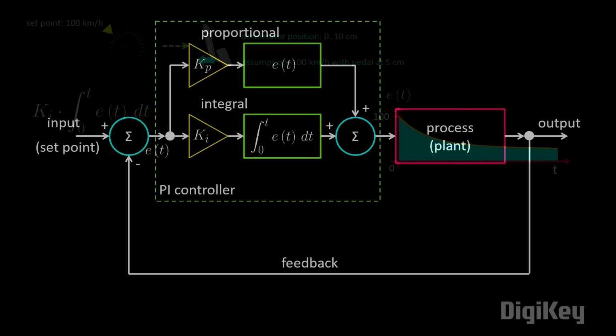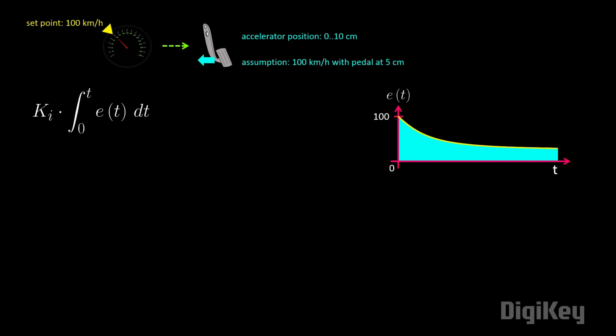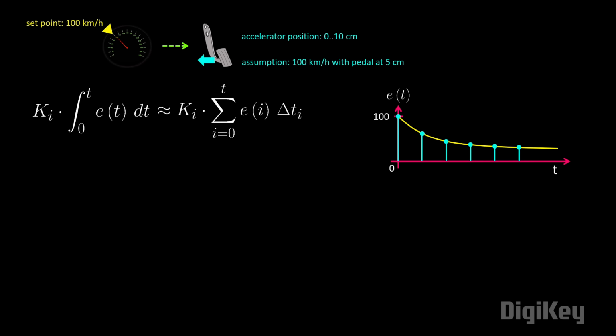However, integrating this unknown error function is often impossible for most real-world systems. So we can take an approximation of that integral. We simply sum each error term over time and then multiply that accumulated value by our Ki constant. Note that for a true summation approximation, you should multiply by a delta t interval time. To make our calculations easier, we can assume that this is 1.